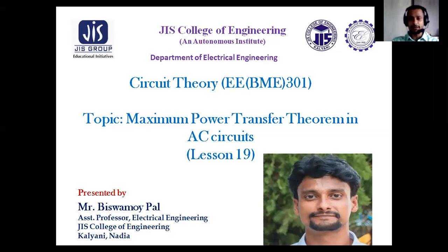Unlike the superposition theorem, Thevenin's theorem, Norton's theorem, unlike all those theorems, the maximum power transfer theorem will not be applied to determine current through a particular branch or voltage across a particular branch. Rather, it will determine the value of load resistance or load impedance in a circuit for which maximum power will be transferred from source to load side.